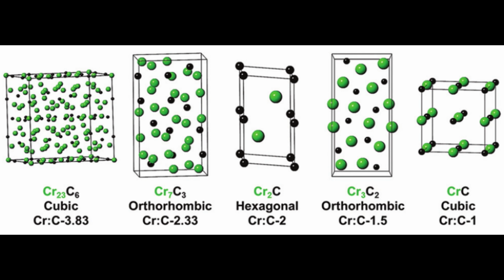It's going to have a very different shape, and it's going to be in a very high stress state because of that carbon that's stuck in there. And that's where the term interstitial compound comes from, because the carbon is trapped. The carbon is trapped in the interstices.